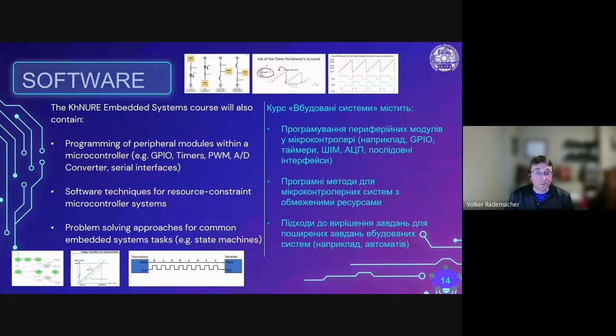Also, the peripherals in your microcontroller will contain features that allow you to control real-life switching hardware. For example, little delays between switching between upper and lower switches or MOSFETs within bridge drivers. Not in extensive detail, but just to mention that these features exist.